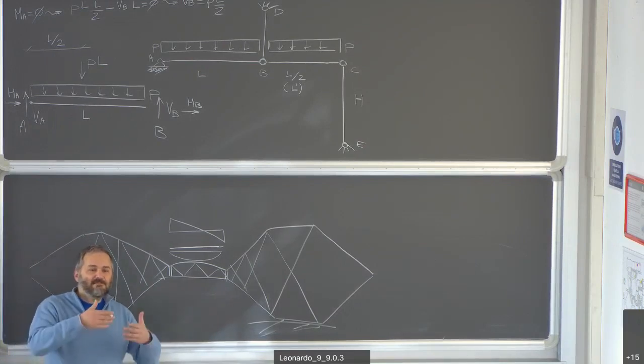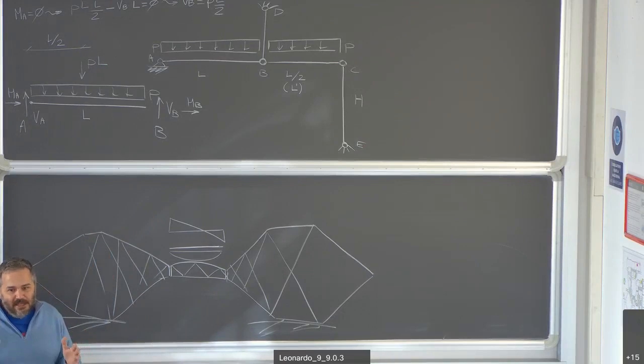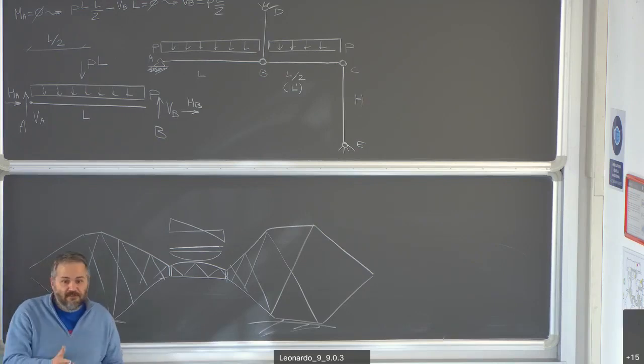As a matter of fact, it was conceived in such a way that it was statically determinate, so the failure of one member determined the failure of the whole structure, because that's what statically determinate structures are subjected to. When something fails, everything fails. Okay?